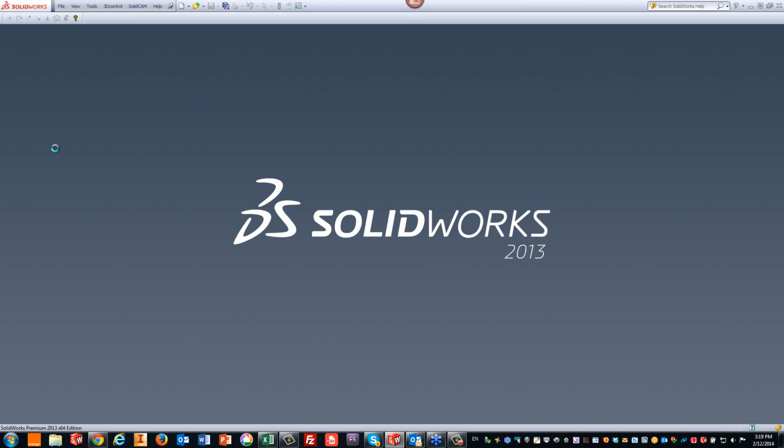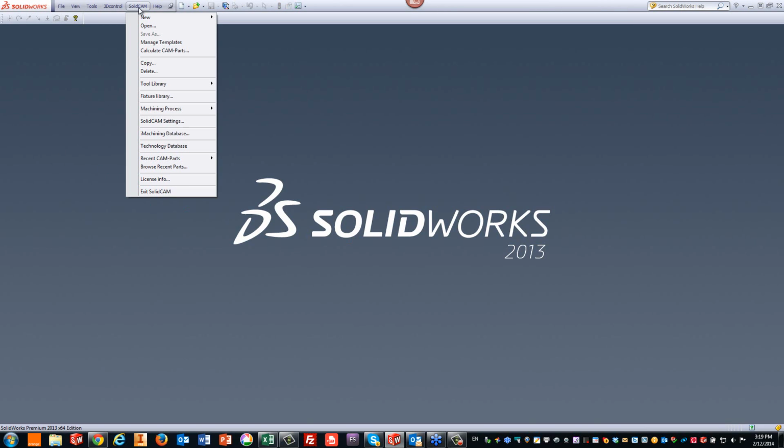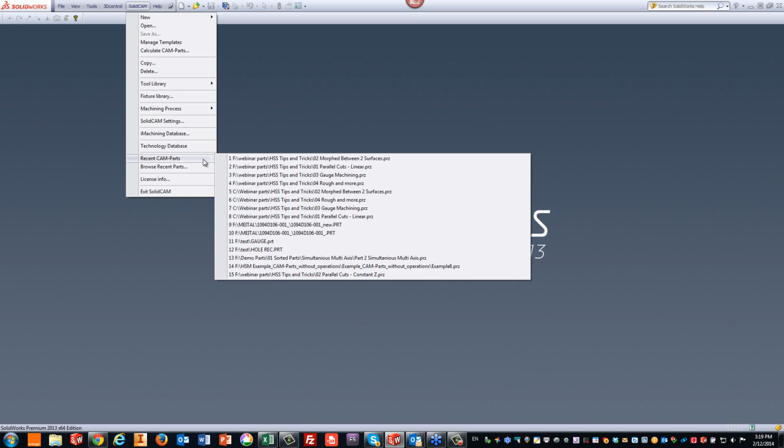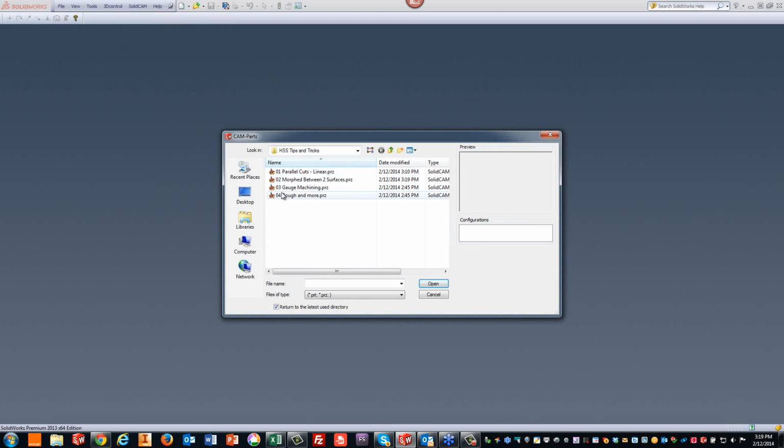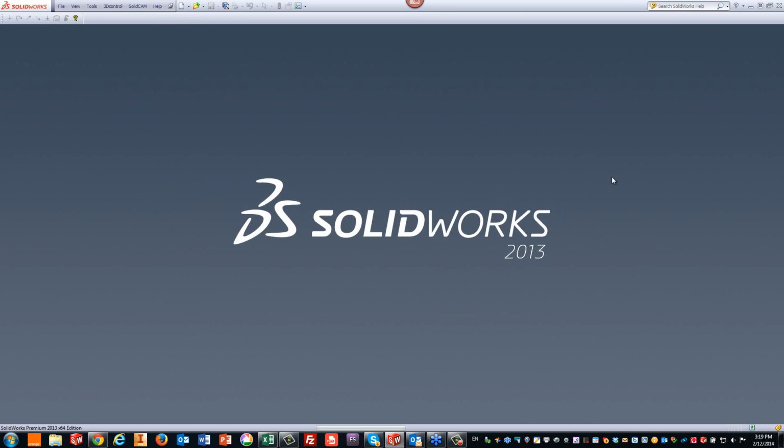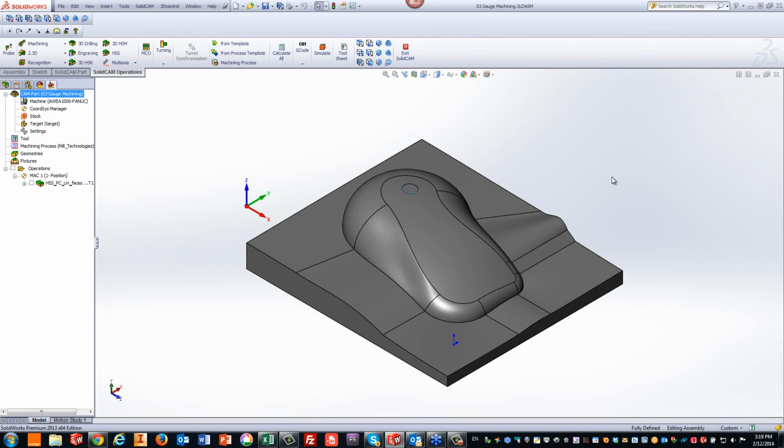And this next one is actually a little bit of a trick I've seen using 5-axis, and I want to use it in HSS as well. We have what we call in HSS gouge control. Now, gouge control is always meant for what? For controlling, to make sure you do not touch surfaces that you don't want to machine. But in this particular case, I'm actually going to show how I can use the gouge control to actually machine the surfaces that I want to machine.